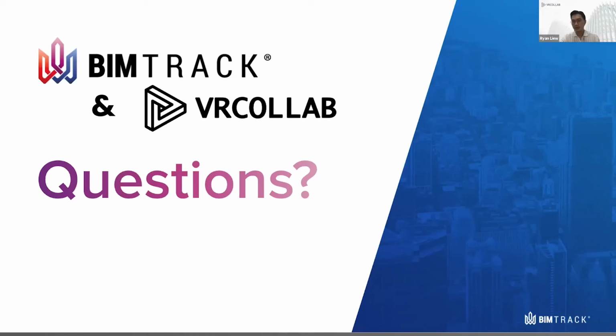If you're using any one of the BIM authoring formats, so let's say Revit, AutoCAD, we have a plugin directly to bring those in. SketchUp, OBJ, FBX, IFC, drag and drop into the VRcollab software. CDE integrations or issue management integrations, for example BIM Track: select the project and then click import into VRcollab. So really everything is one click. Don't worry about it. It really is that easy, folks. You can just drag and drop and get in there.